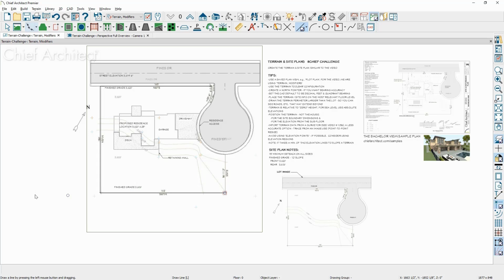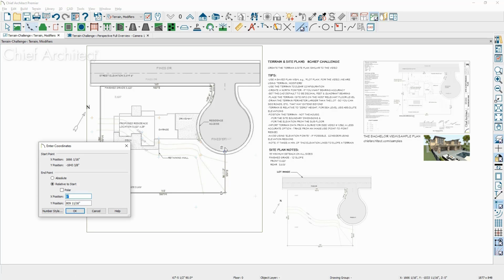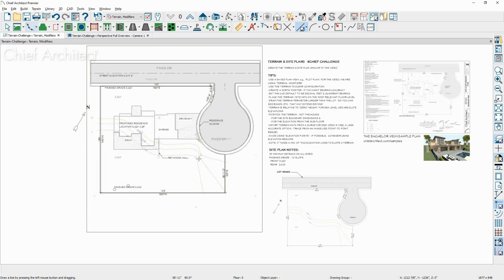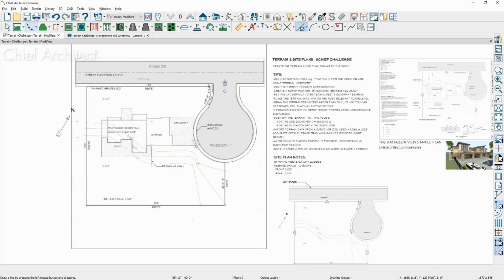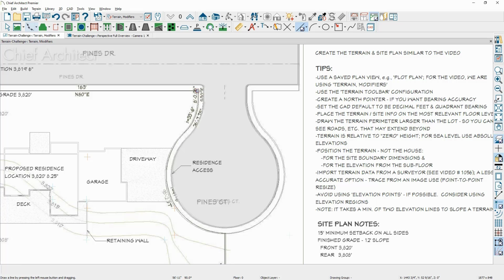And then for this line, we'll go ahead and click and drag up. Again, I'm pressing the tab key as I do this. This number should be 56 feet 11.2 inches. And then for the last line segment, here's what I'm going to do. Let's zoom in just a little bit further. I'm going to come down. I'm not going to worry about pressing the tab key. That's 6 feet or so. Draw a line segment there. I'm going to draw one more line segment in here. So I have 2 line segments, and then the last one I'm going to come over and snap that on.